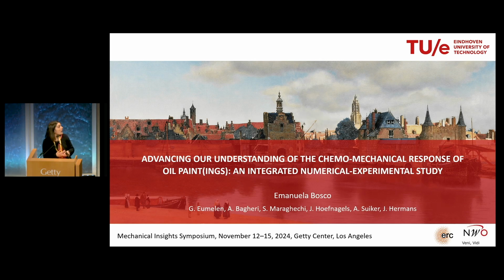Without a microphone, the question was, what materials do you use to apply your speckle pattern? How do you apply the speckle pattern? The speckle pattern for the DIC? What do you use to apply that with? So we use an airbrush. Maybe I can show you.